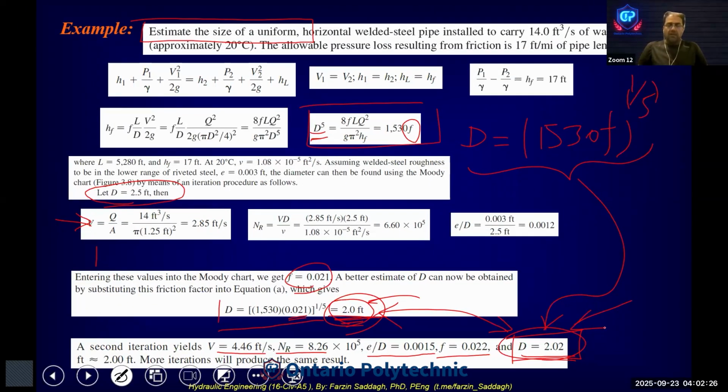One question: if we reduce the diameter of the pipe, what happens? Increasing of friction, or actually increasing of head loss, or decreasing of head loss? Which one? Decrease, because the friction area decreases. No, the velocity is higher than the previous one when we make the diameter smaller, so the head loss should be bigger than the previous one.